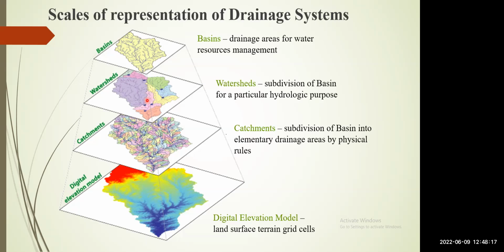Now, whenever we have a pour point at one location, we can find the watershed of that specific area, and how much area it covers, calculated from one place and covering the whole place. For example, if water is coming from one stream, that whole area is connected with this single stream, so we can know how much water will flow from that whole area if there is some precipitation, some other occurrence of rainfall, or a flash flood.